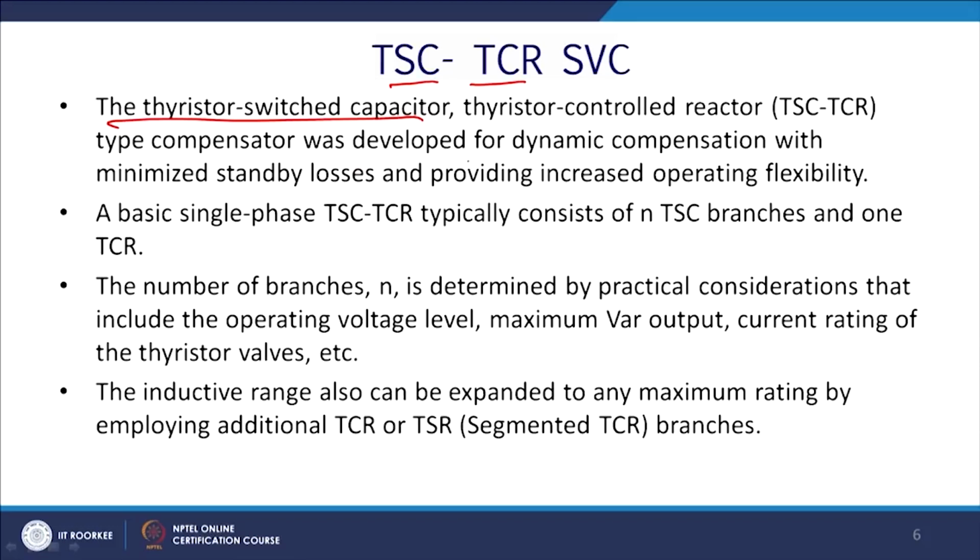Actually, the compensator was developed for dynamic response with minimized standby losses, providing increased operating reliability, because you can also frequently turn on and turn off this TCR that is already there, and apart from that you have the TSC. So, that also can be turned on very frequently.